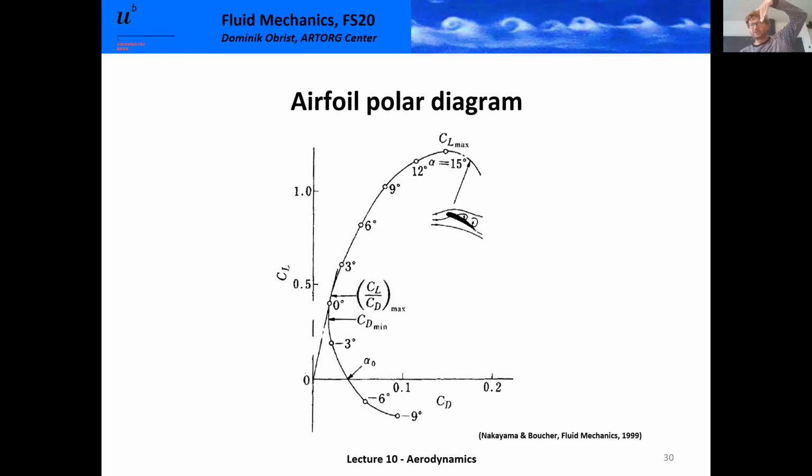If you want to do a nosedive, straight down, your direction of flight is straight down. If you had any lift, you would go like that, you would recover. So if you want to, in an aerobatics program, fly straight down, or, of course, for that matter, also straight up, you want to fly in this condition at the alpha naught, at the slightly negative angle of attack, in order to create 0 lift, and so on.